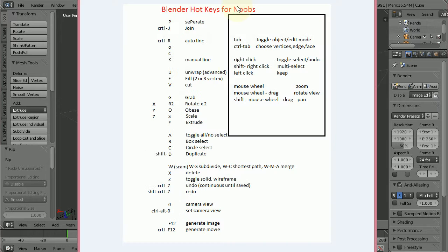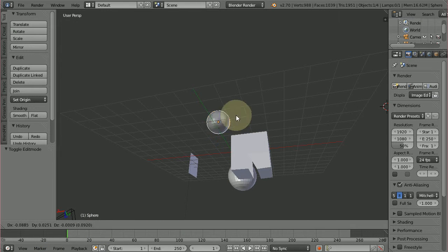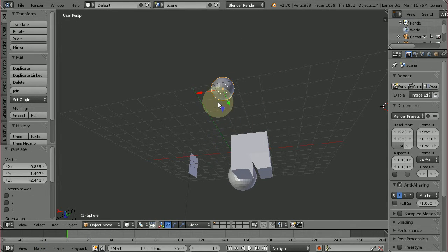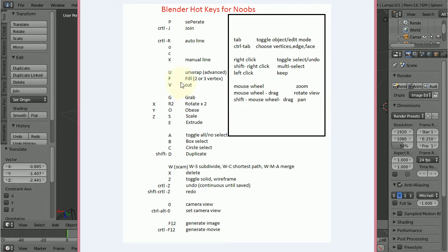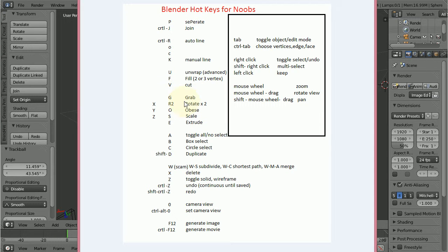Okay. So G, I've probably done this a couple of times. Let's just, in object mode, I'm going to select that. G moves it around. Circles are hard to rotate. I'm going to go through GRS, G, R, S, and E. Now, rotate, I'm rotating it around. It's got a little square on it because there are two types of rotation. So there was the little square.